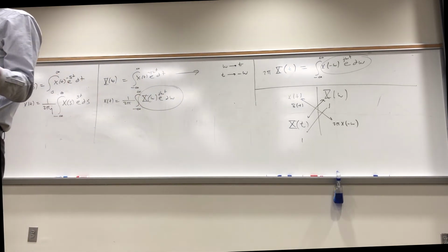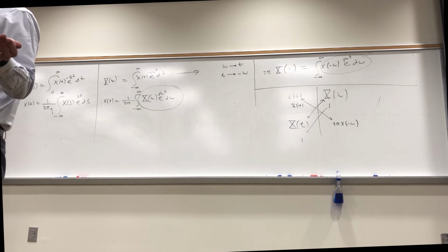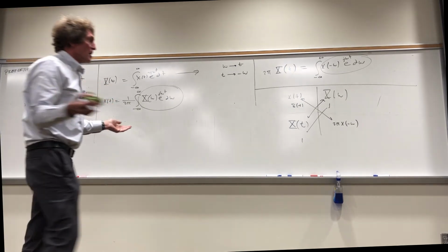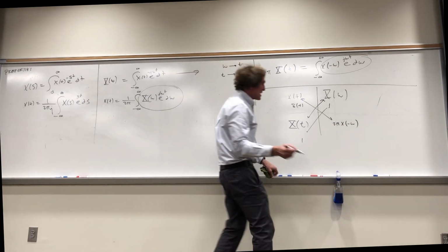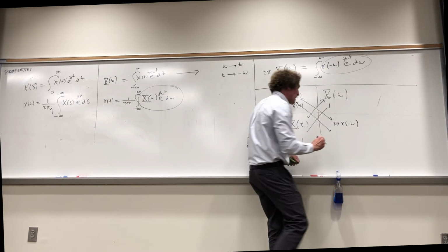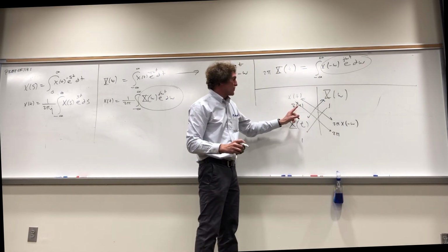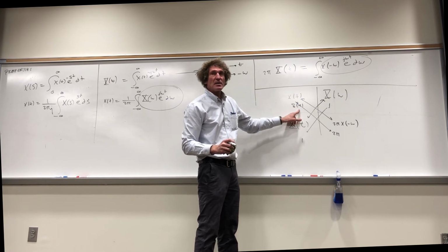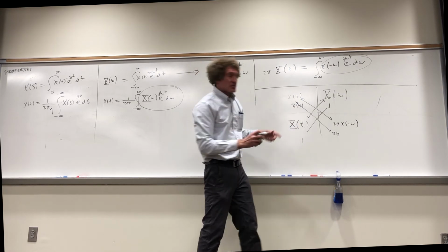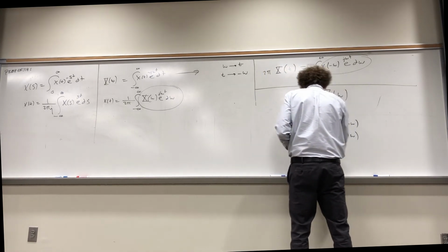Right? 1 all the time is just like a DC battery of 1 volt, isn't it? There's never a time-varying change. Well, duality says that in the frequency domain, the signature looks like 2 pi, and I take this functional form, which is delta t, but now I replace the t with a minus omega. Got that, class? So now I have delta of minus omega.